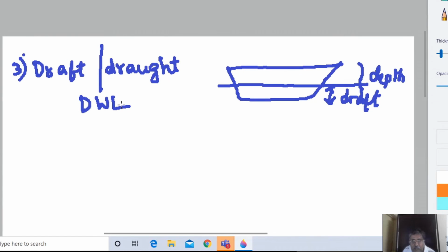So that is a question, right? I think that is what you are saying. Because the waterline can change, obviously. When weights are added, the ship will sink. In fact, that is what you are going to do in the rest. But there is something known as a design waterline, which is fixed. The fact remains that as you keep on putting weights, the draft keeps on increasing. This is basically the Archimedes principle that is coming as the next chapter.